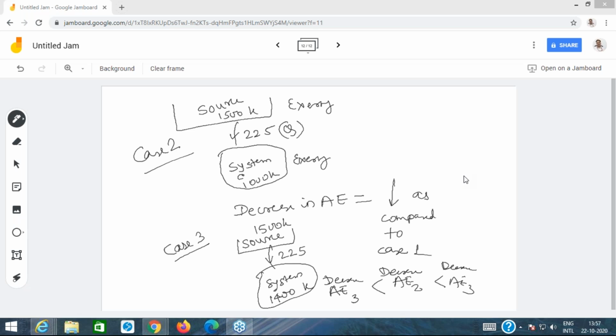So in order to ensure that, we need to make sure that the temperature difference between the source and the working fluid which is accepting the heat is as minimum as possible. That would give you better results, better output from that engine. So that is the insight which we get from the exergy analysis.